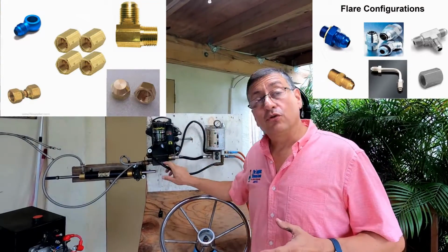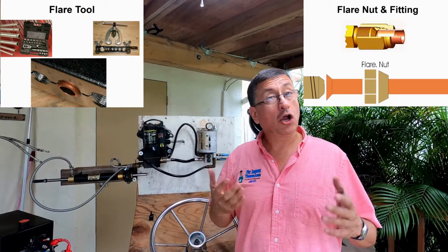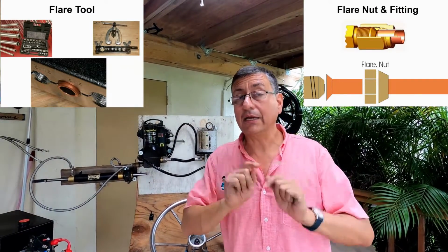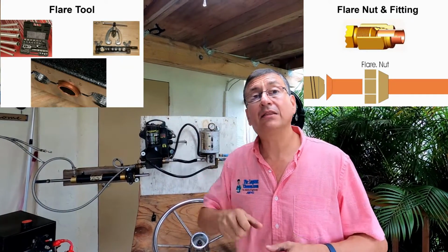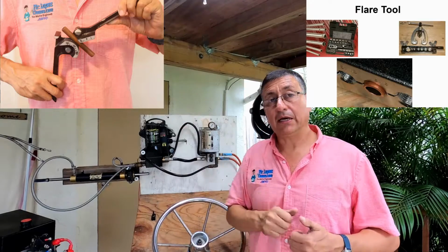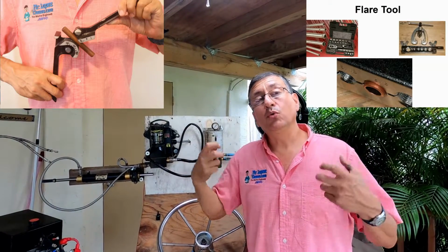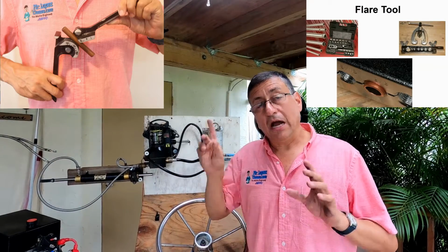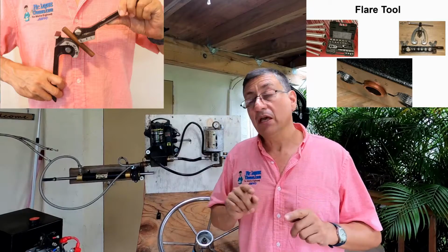For that reason, you can use flexible hoses or you can use rigid lines like in copper or stainless steel. In that case, you need the flare tool in order to do the flare, and the bending pipe, like the bending pipe that you have on the screen, to bend the pipes and to do the flares. And always use fittings marine approved.